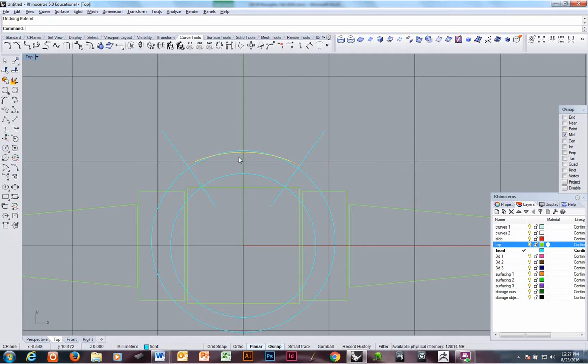But I'm going to show you what I would do by habit, just because I know how often that doesn't work out. By habit, what I would do is select these two new pieces of geometry that I want to keep. Copy, Control C, copy to the clipboard, so they're outside of Rhino. Okay? And then I would undo.